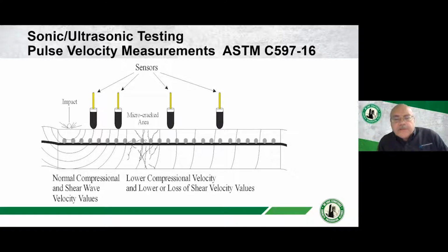Rendition of that 4-sensor array is here, and we talked about the velocity measurements. ASTM has a procedure to record pulse velocity measurements, and we follow that. So as you're dropping a pebble into a pond of water and you see the rings echo out on the surface, there's a third dimension where that ring or that pressure wave goes down to the bottom of the pond and then is reflected back up. That is a combination of what we're looking at here.